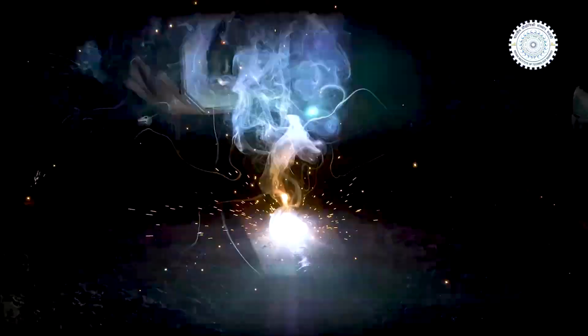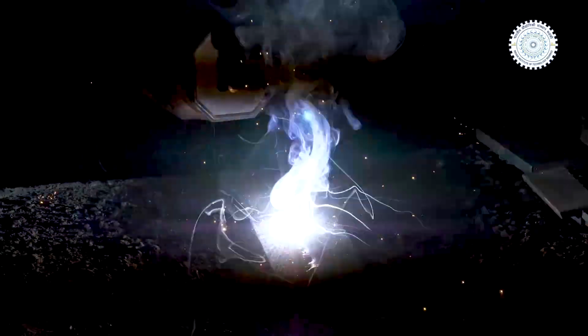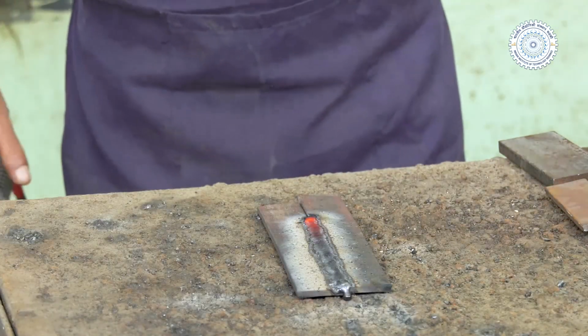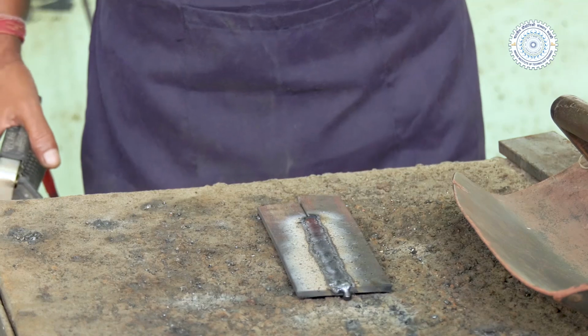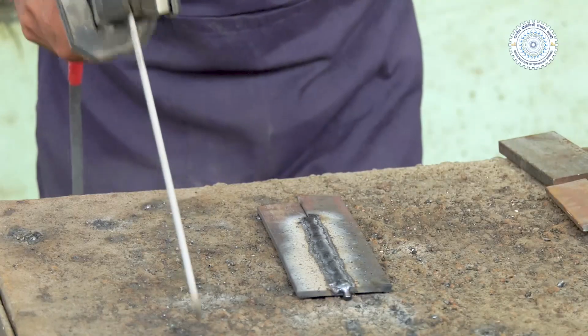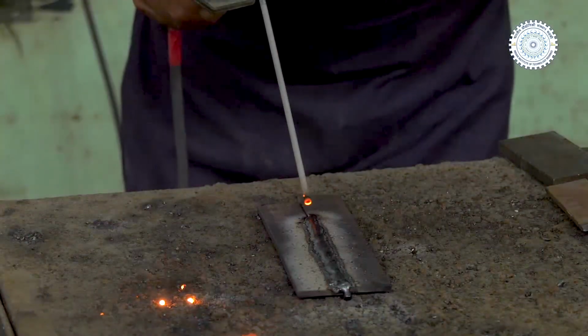The process is quite fast, but it requires a lot of skill in order to manipulate the arc, control speed and the movement of the arc, and avoid the sticking of the electrode with the workpiece. The welding current and the speed of the movement of the arc determine the amount of heat being supplied during the welding. This is how you can see the weld is done, and here we have replaced the electrode, and again the welding will be continued from where it was left.